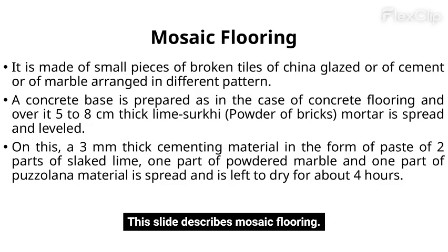This slide describes mosaic flooring. It's made of small pieces of broken tiles, china, glazed, cement, or marble, arranged in patterns. A concrete base is prepared, followed by a 5 to 8 cm limestone mortar layer. A thin cementing material is spread and left to dry.